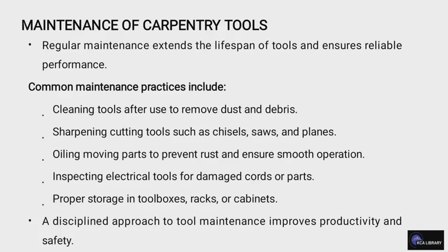Let's look at maintenance of carpentry tools. Regular maintenance extends the lifespan of tools and also ensures reliable performance. Common maintenance practices include, one, cleaning tools after use to remove dust and debris. You also need to sharpen cutting tools such as chisels, saws, and also planes.